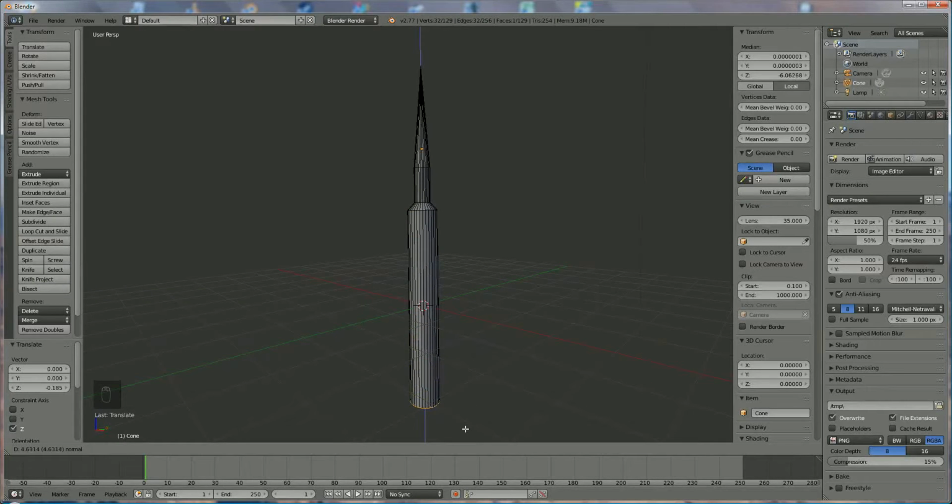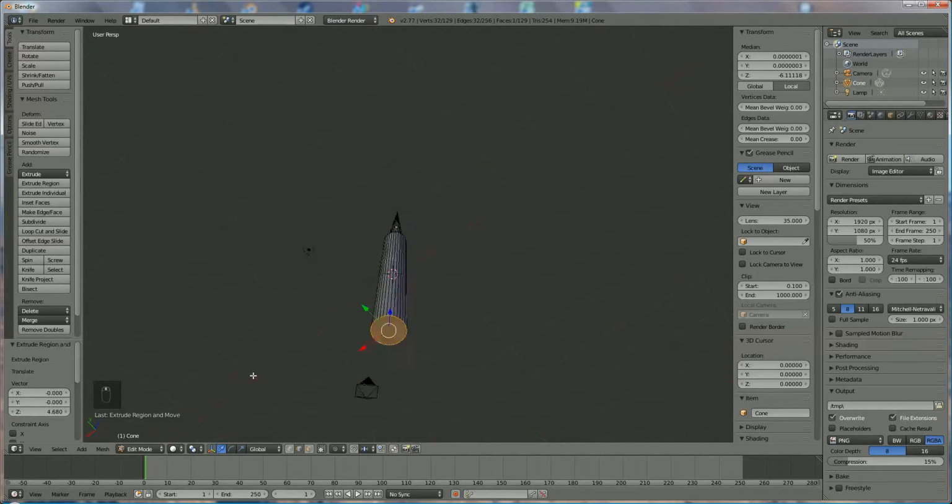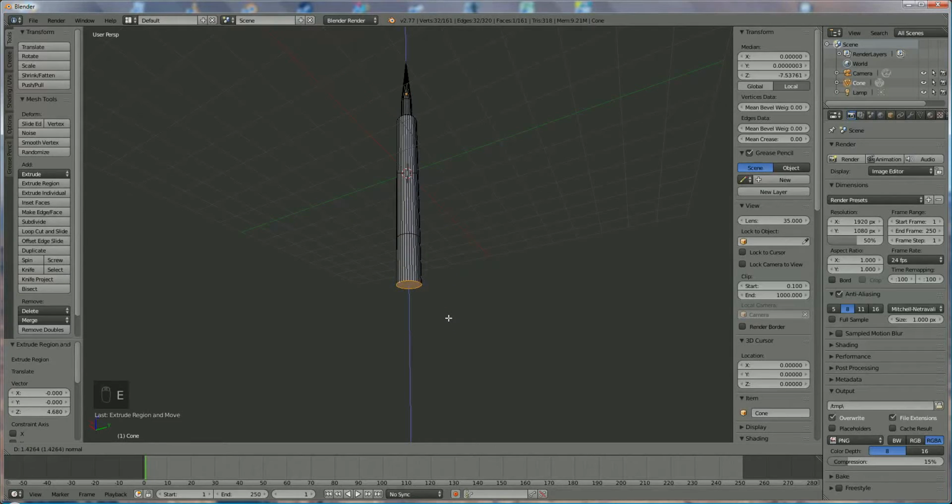and there should be something looking like this. Later on we're going to change that. The rest is also a little larger, so E again. Let's say a third of the rest. We press the left mouse key and we press S to shrink it, so we make that a little conical, like that. We're going to press E again to enlarge it, and enlarge it until here.